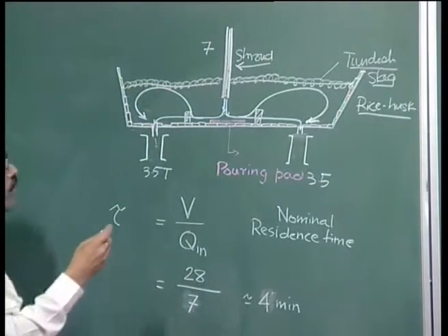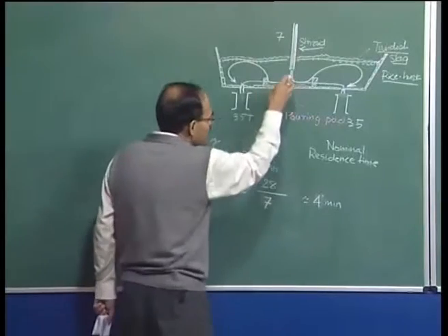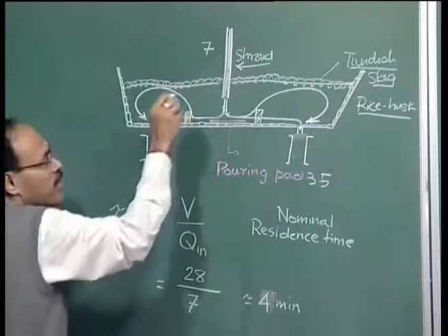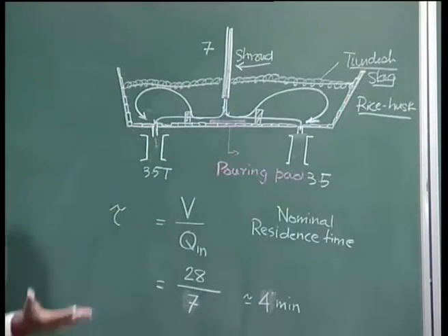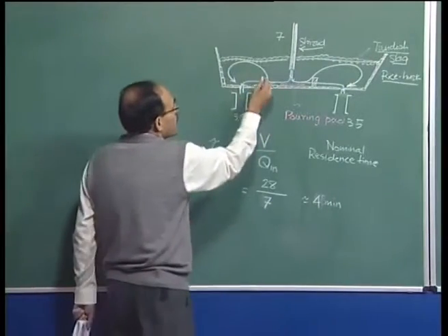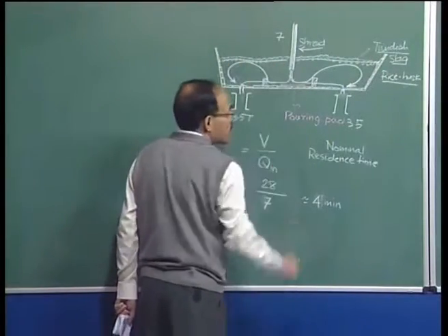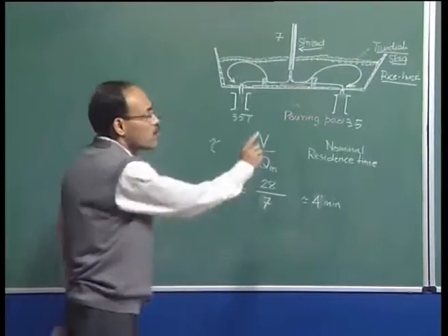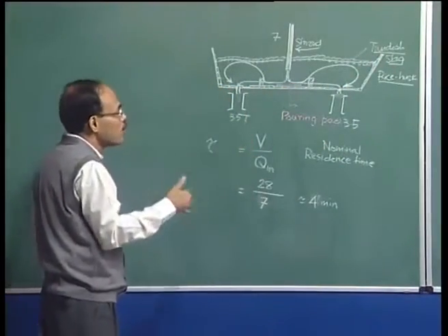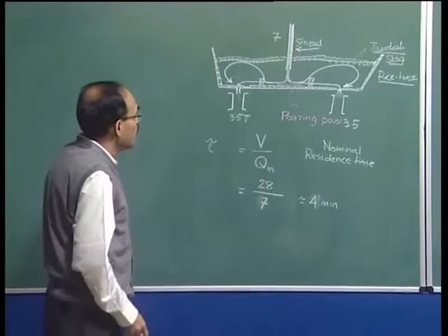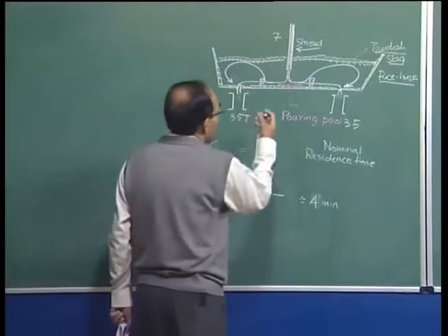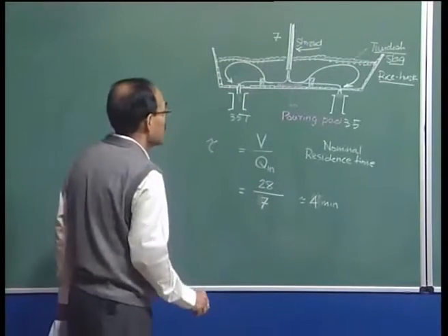So, if we can allow or force liquid steel to spend some more time in the tundish itself, in that particular time, lighter inclusions will tend to float, and once they float, they can be absorbed by this slag, which is always there. So, the slag is freshly prepared. It is not the ladle slag, but the tundish slag is made out of rice husk and different chemicals in order to create a conducive environment for the absorption of the harmful non-metallic inclusions.